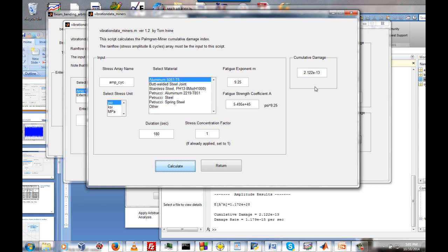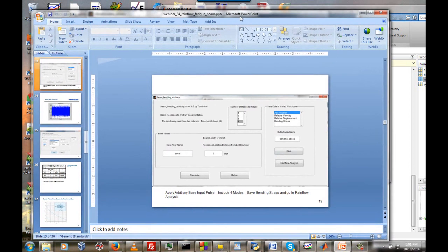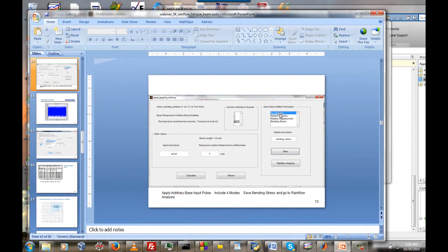And at this point you should be saying, well, my goodness, the criteria for failure was damage equal to 1, or if you want to be conservative, the criteria for failure was 0.7, and we're so far below that limit that fatigue is just not a concern at all. And to that, I'm going to say, yes, that's true. Those are all true statements. So in this case, fatigue is just not going to happen.